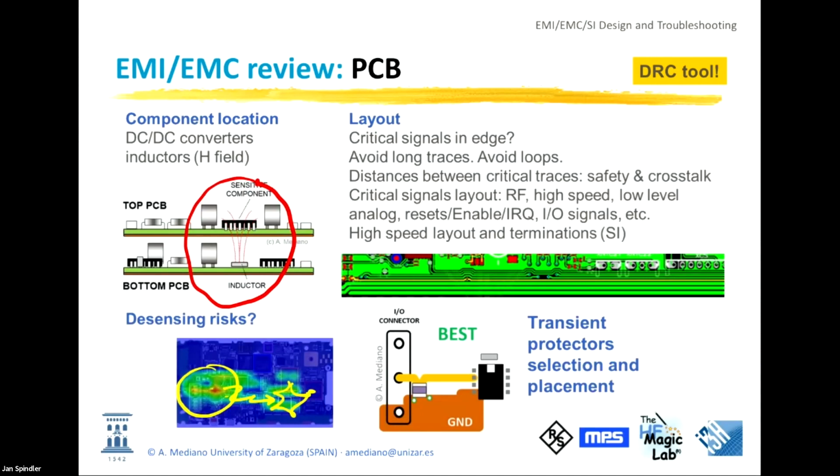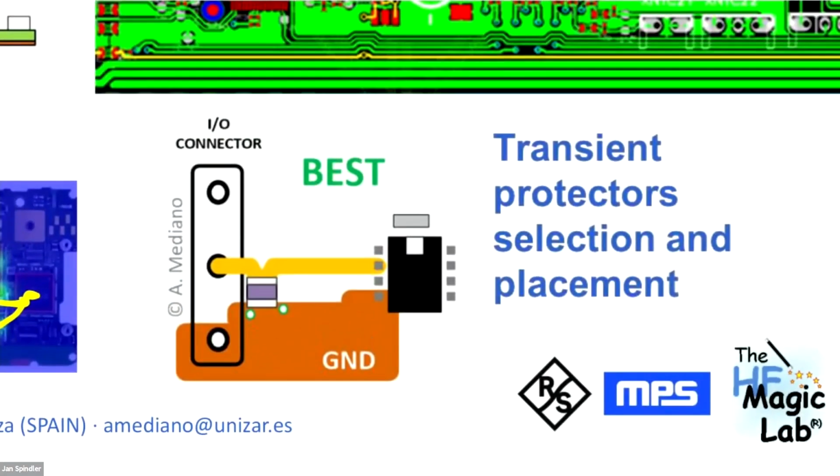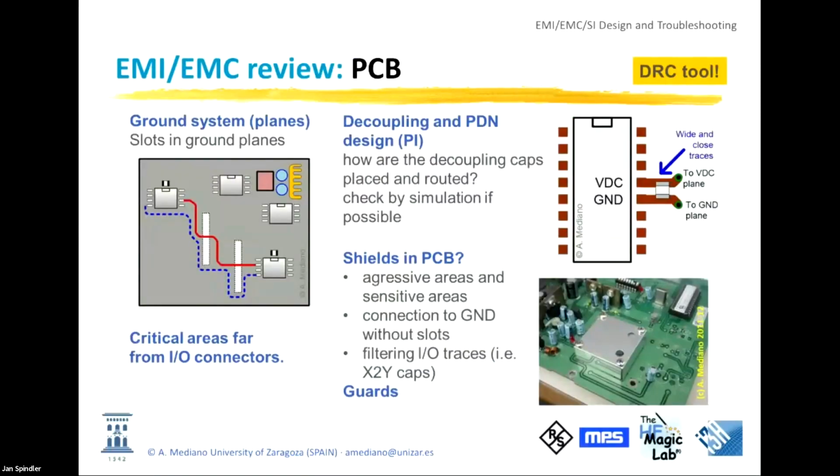Okay. What about the layout of protectors or filters? You need to apply radio frequency techniques. You need to use short and wide traces, good connections to ground, or things like that. If not, the protector will not work as intended. This is part of the layout review.